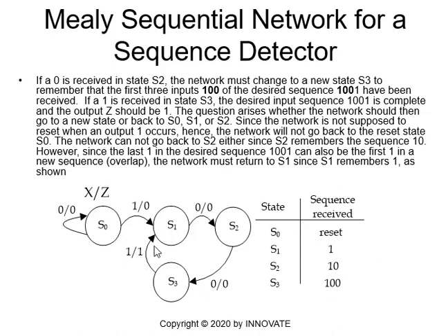Okay, and I have to go to S1 to allow overlap to remember the last one. So S1 remembers the 1, the first bit in the sequence, and it happened to be the last bit in the sequence here. So I have remembered the 1 because S1 remembered 1. So in case I receive 1001, you will get an output Z again, and so on and so forth, in this loop.